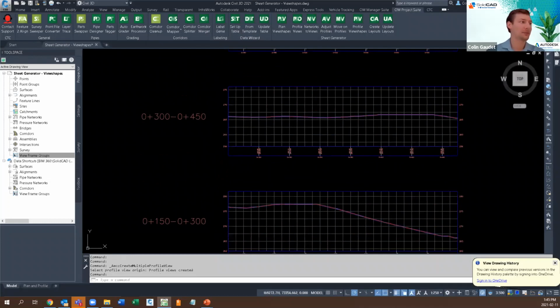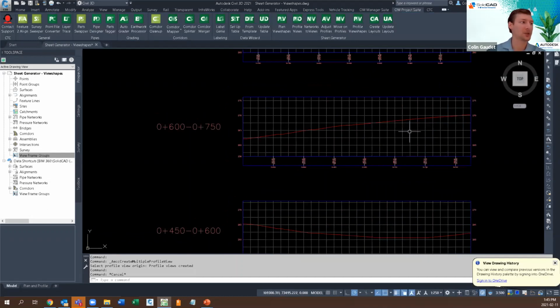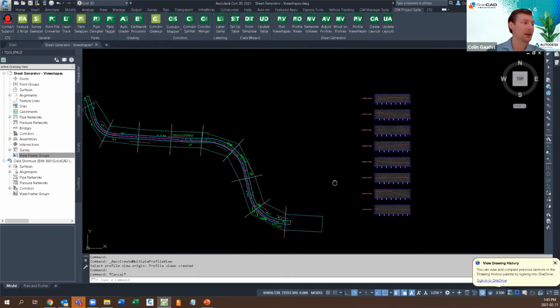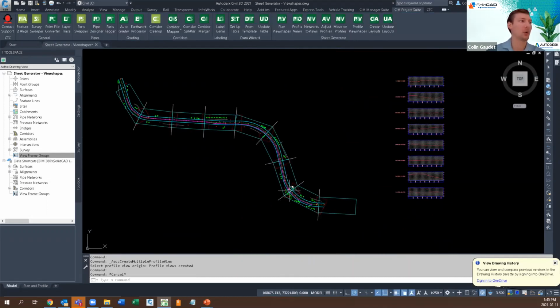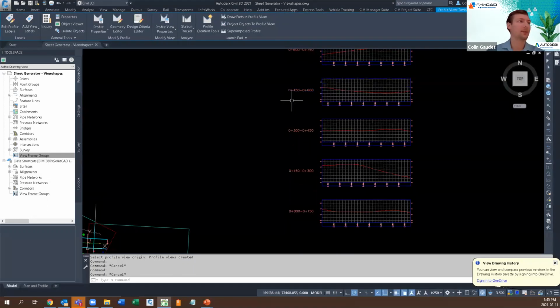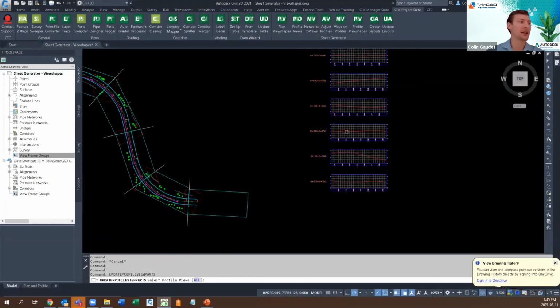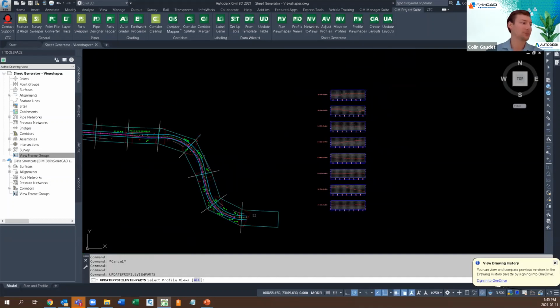We've got our surface, and it looks like the elevations are all right. Well, we need to come back here. We need to start adding our networks. That would be the next portion of this workflow. So unlike the native Civil 3D tools, where we have the option to add the entire network to each of these profiles, the CTC tools allow us to just add the network objects that are in view in each of these profiles.